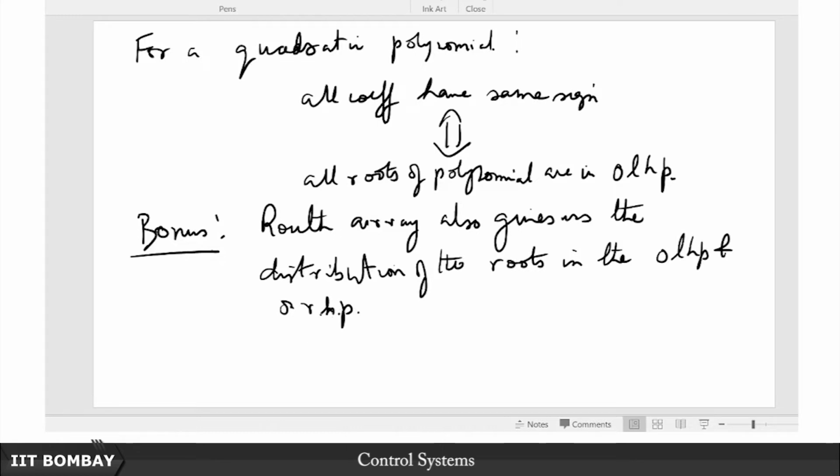That's actually more interesting because it's a singular case. But for now, you can think of it like this: not only does the Routh array tell you if all your roots are in the left half plane, if they are not, then it will also tell you how many are in the left half plane and how many are in the right half plane. This is a fact that does not readily follow from the analysis, or the sketch we have given so far about this algorithm, but we will visit that shortly.